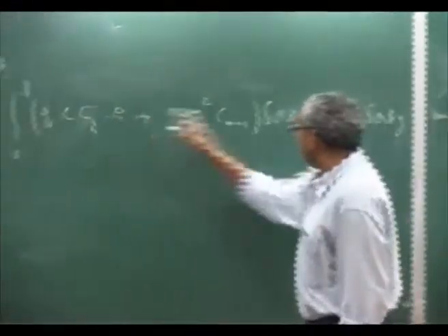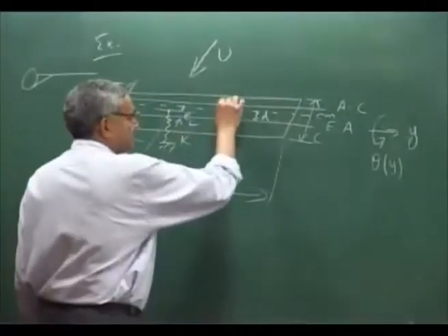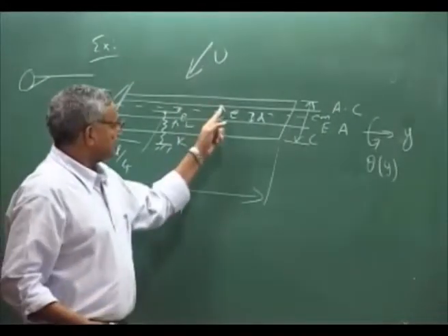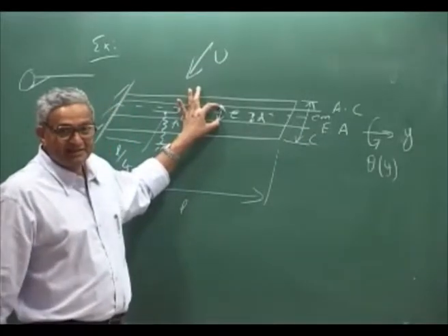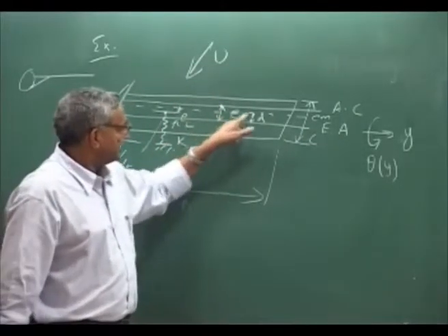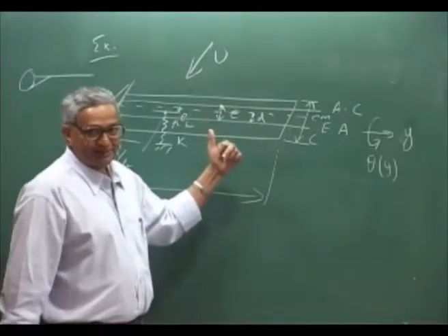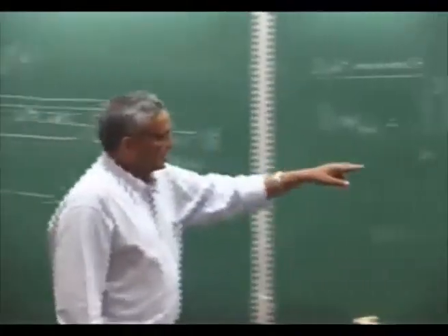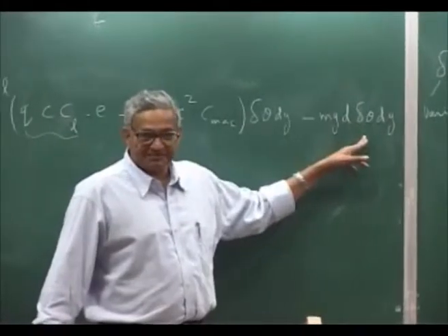Because E into delta theta is, if you take, the force acting on this, which is normal, the virtual displacement at that point is delta theta into E. Whereas the force acting on the center of mass line is down, the displacement that comes out is D into delta theta. And the minus sign because the force and the displacement are in opposite directions.